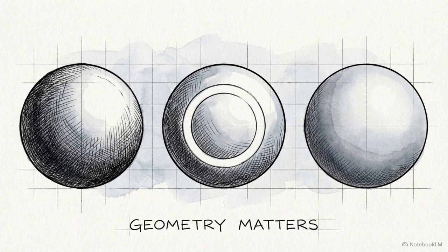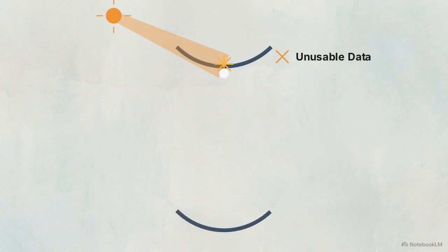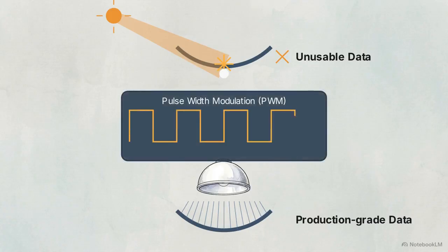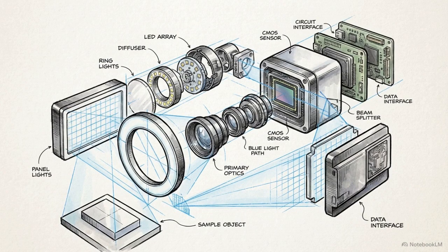When visible light is appropriate, the geometry of the lighting strategy has an immediate, measurable impact on classification accuracy. This 3D model illustrates standard lighting creating blinding highlights on reflective parts. Dropping a diffuse dome instantly eliminates glare. Facilities embed pulse width modulation controls to adapt to varying factory conditions. These hardware compensations ensure consistent data, improving downstream detection regardless of environmental shifts. Precise control over the physical environment establishes the data baseline. The hardware dictates the absolute maximum ceiling of the software's capability.